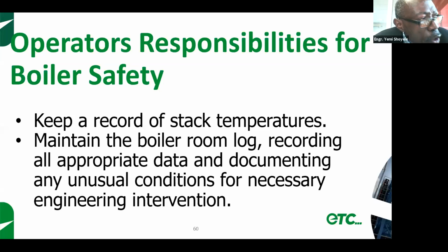Well, I don't have the figures here, but it's probably not 10 ppm or below 10 ppm, something like that. But there is recommended boiler operations maintenance. Again, even your boiler manual manufacturer will have specified that. But I think it's in the range of something like about 10 or 12 ppm. It's as low as that, very low. If it's possible to get it to 0, then you should do. But I know there will always be some.